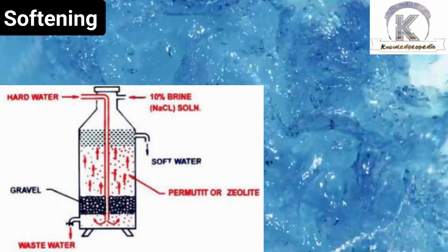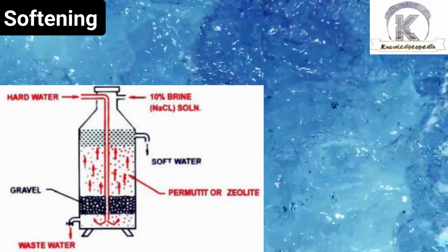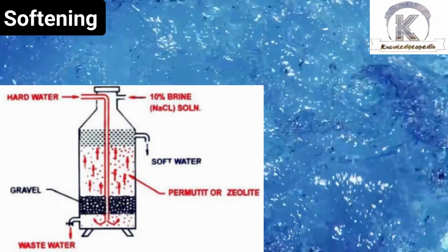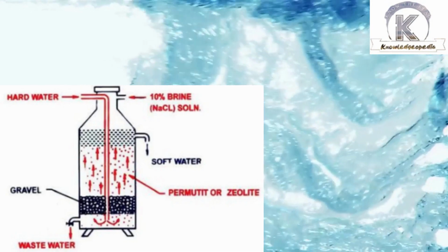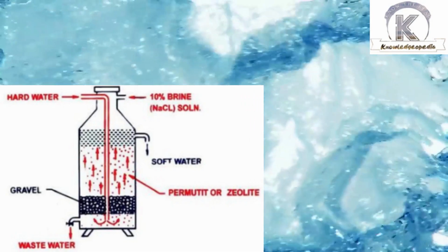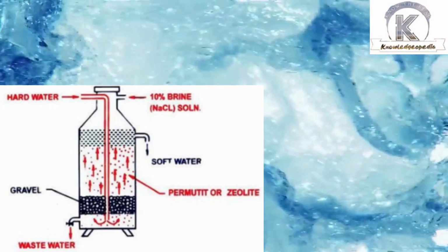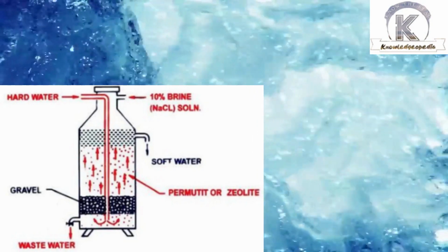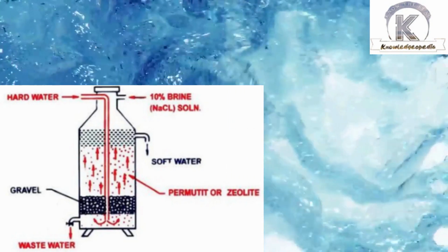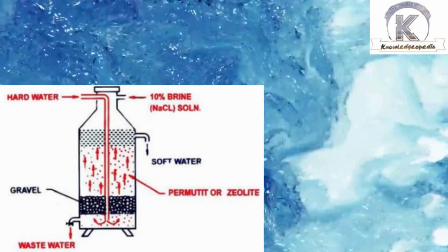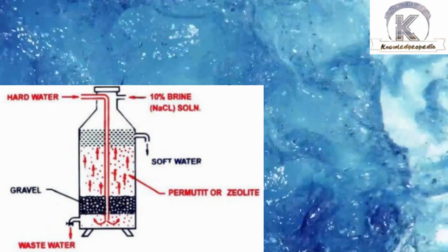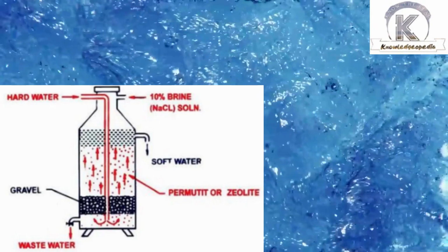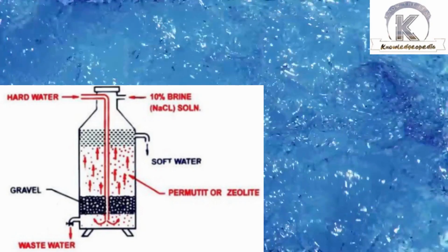The Drinking Water Inspectorate says that water with a sodium content of up to 200 ppm is safe to drink. To achieve this level, the final step of softening is carried out. In simple words, soft is the opposite of hard, and making water soft from hard is called softening. There are 4 methods of water softening: ion exchange, salt-free, reverse osmosis and magnetic. Out of all these, ion exchange using zeolite is the most widely used and cheapest process. Zeolite softening removes permanent as well as temporary hardness of the water. It occurs when magnesium and calcium zeolites, which are insoluble in water, get precipitated.